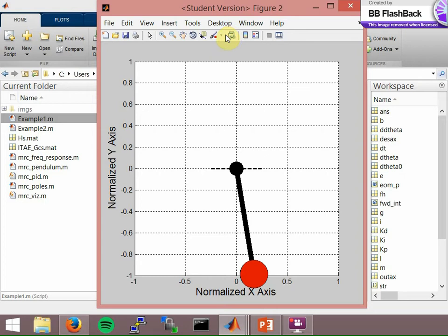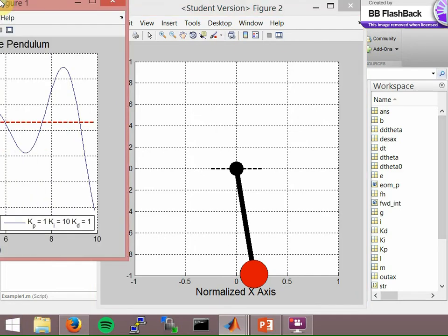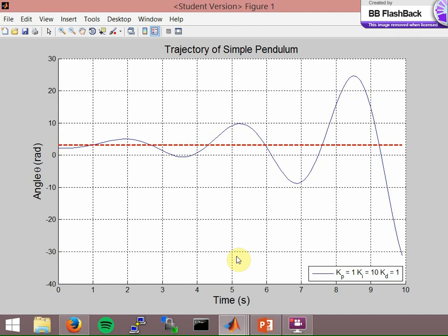If we're using the inverted pendulum example, what that means is that we want to make sure that we're stable enough that we're able to get the pendulum from that initial position up to that upright position without it going crazy like we're seeing here. And if you take a look at the time response, this is something that you'll see in a lot of unstable systems, right? We have our desired position by the dashed line, and the blue line is the time response of the system. You can see that it's starting at an initial offset, and then it's overcompensating, continues to overcompensate on the other side, and continues to overcompensate. So that oscillation drives our system crazy, right?